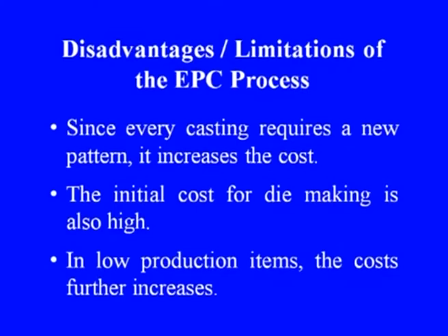Now, let us also see the disadvantages or limitations of the evaporative pattern casting process. Since every casting requires a new pattern, it increases the cost. The initial cost for die making is also high. In low production items, the cost further increases.